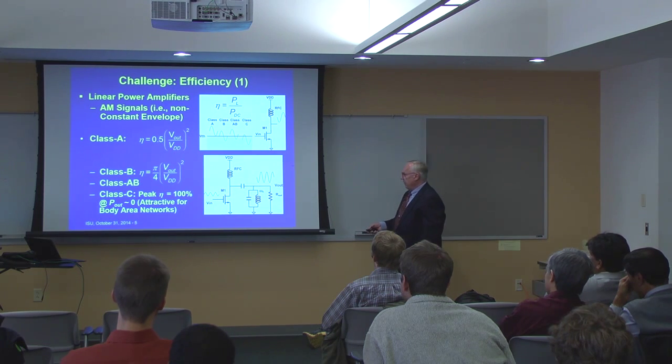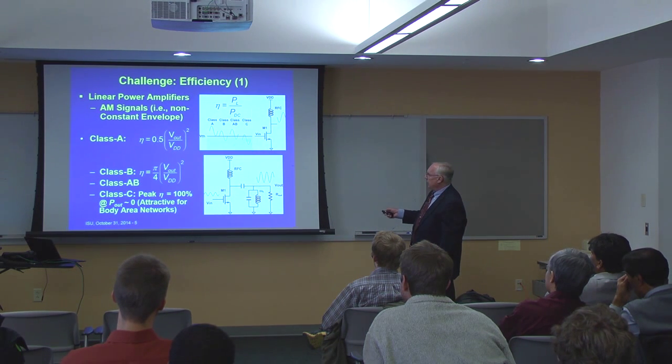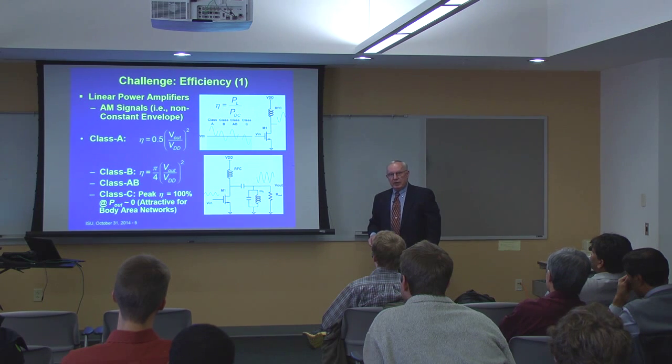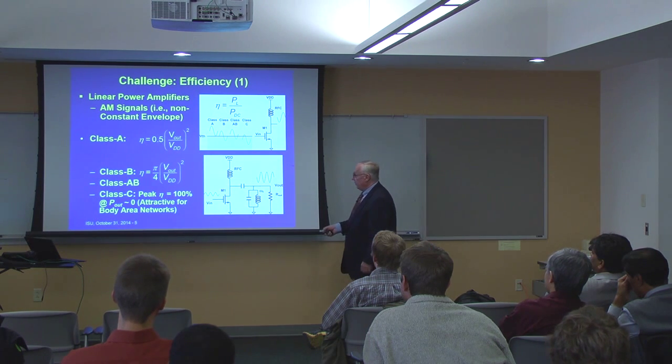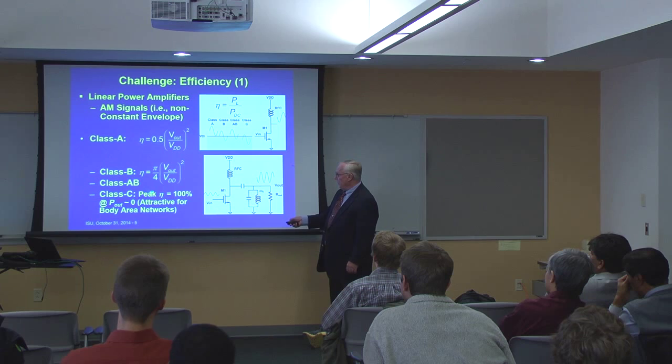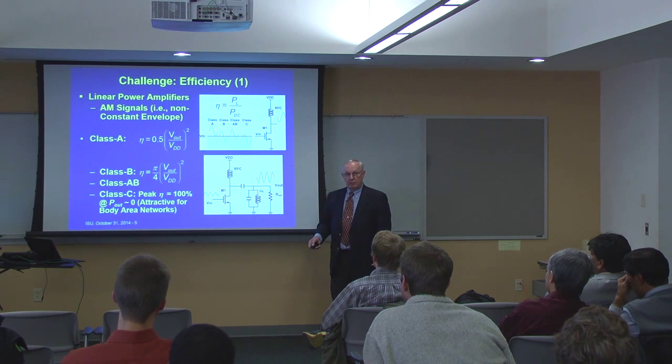And another class that hasn't gotten much attention is class C, where you operate the device so that it's hardly ever on. So you think, what's this useful for? Well, it has a great feature. If you look at the maximum efficiency of this thing, it's 100%.